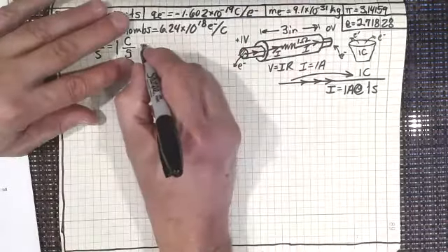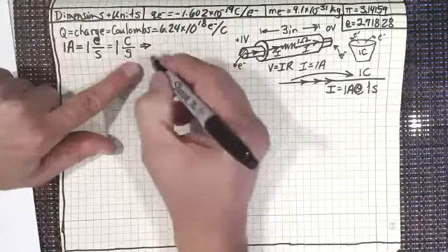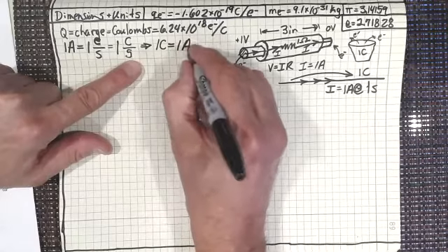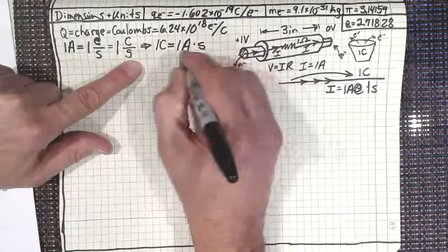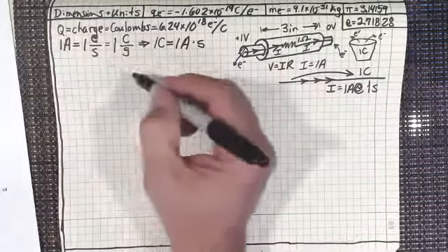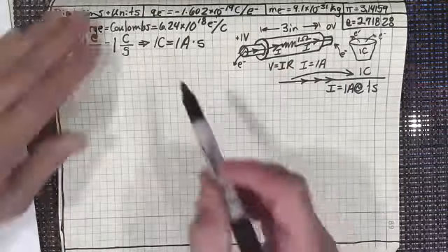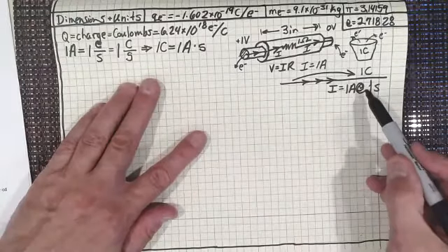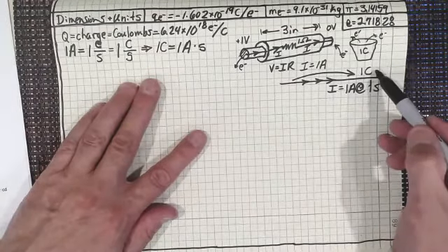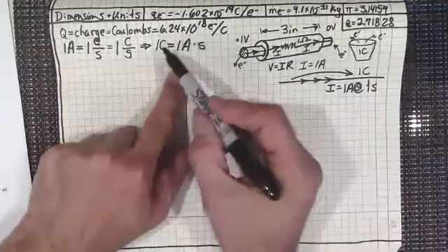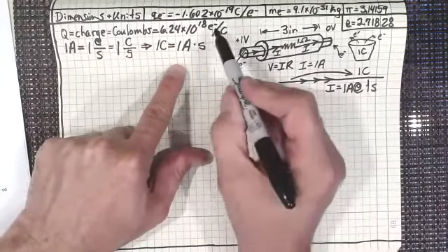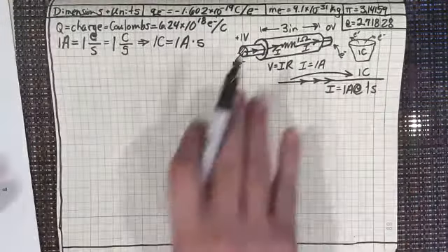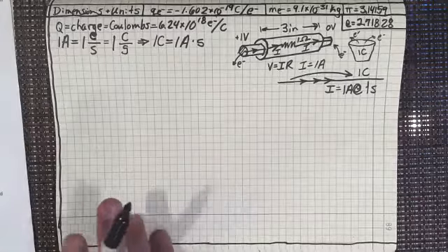Now you could say, okay, we could say that it's 1 coulomb per second, or we could say that 1 coulomb equals 1 amp second. Notice I've got the dot there. It's not amp per second. Of course it's not. Look at the math. Look at the algebra that we've got here. 1 coulomb equals 1 amp second, and that would mean amp for 1 second gives me 1 coulomb of charge. That gives me 1 bucket, or 6.24 times 10 to the 18 electrons in 1 second. 1 coulomb. All right, does everyone understand that?